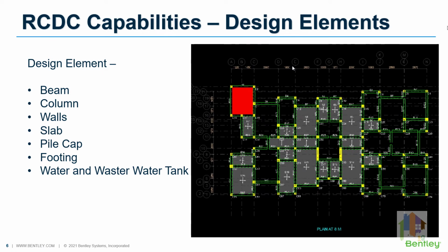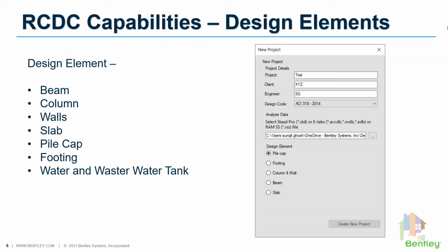RCDC uses the panel method for the design of slabs and does not carry out any analysis. The bending moments and shear forces for design are calculated based on the empirical method. You can also design isolated and pile cap foundations in this module. In the latest version of RCDC, which is version 10, water and wastewater tank design has been included. You can import the tank module directly from STAAD and perform the design here.